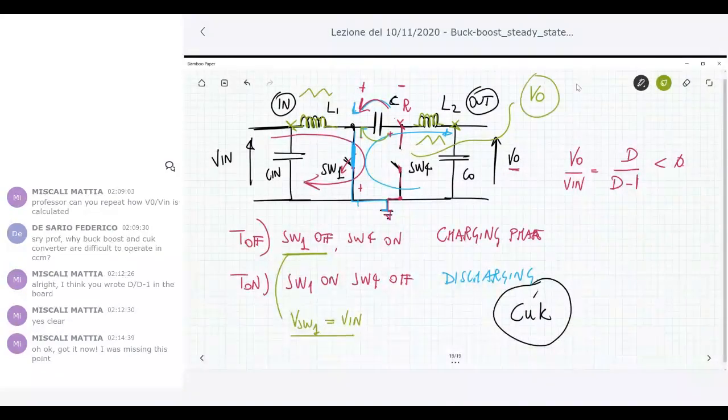Now, this is a benefit again, which is the working voltage across this capacitor. This capacitor has a working voltage which is V in minus V naught. Since V naught is negative, it is quite a large voltage.